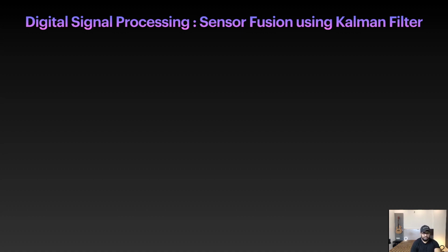You need to do sensor fusion really fast, and that is why Kalman filter is a really common filter when it comes to drones. So technically speaking, you can definitely use a complementary filter, but it is not as fast. It's really costly on memory and space and computation. So in the drone industry, in drone hobbies, the firmware we use, that is the firmware for our flight controller, implements something called Kalman filter and not complementary filter. Maybe some previous firmwares had a complementary filter, but nowadays I've seen everyone using Kalman filters.